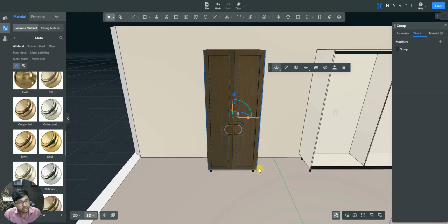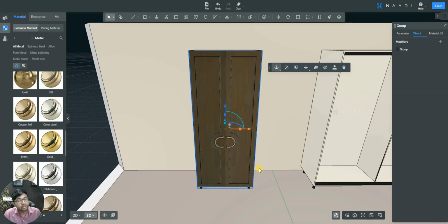And the best part here is, once you have created a custom design shutter, and if you feel like you might have a similar design requirement for another project, you don't have to do this entire process again from scratch. Make sure that the entire shutter is in a group, and once you select that shutter group, it will open up a floating window, right? There at the right you will see something known as import to me, this humanoid icon.